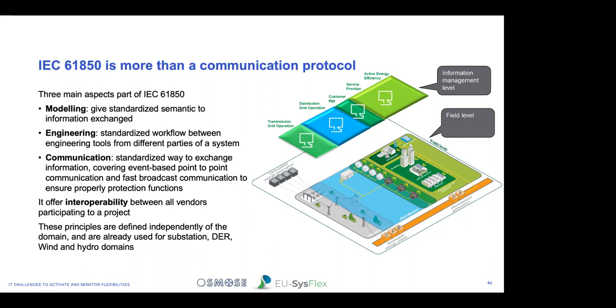And if we look at the smart grid architecture modeling, the SGAM, they already identified two main standards to address this. The first one, CIM, is more focused on the market and the enterprise level, and IEC 61850 for the operation level. Yes, 61850 is more operational than CIM,